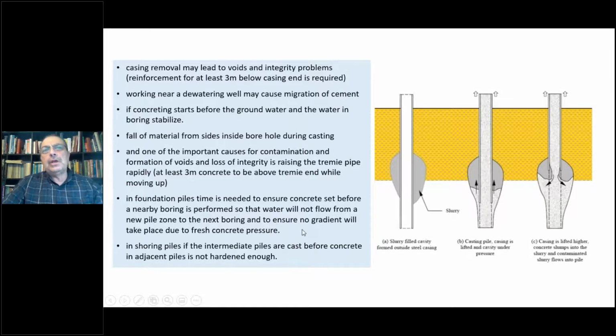That means you need to keep enough distance between a new pile being installed and an old pile, if the old pile is not hardened yet. So if you have a piling sequence in the same day, you need to choose your pile locations away from each other while sequencing your installation.